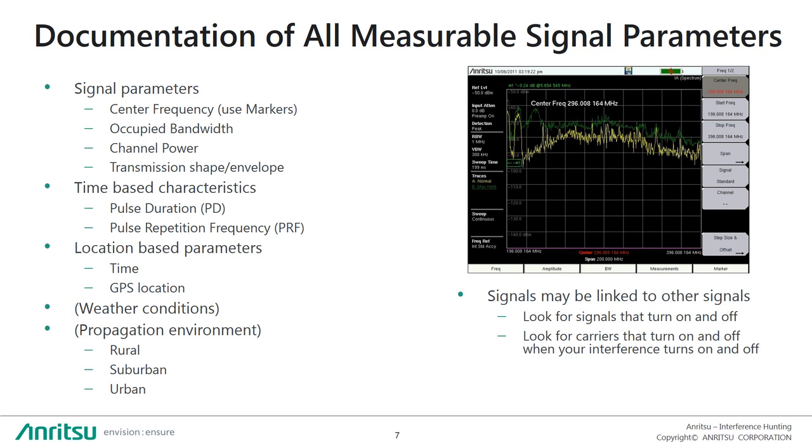Being able to get a spectrogram view is another way to get time-based information. One nice example I have is from the US, where interference occurred in an area for a few hours every Sunday. Once this time pattern emerged, the source was finally found to be the wireless microphone used by the local church minister.